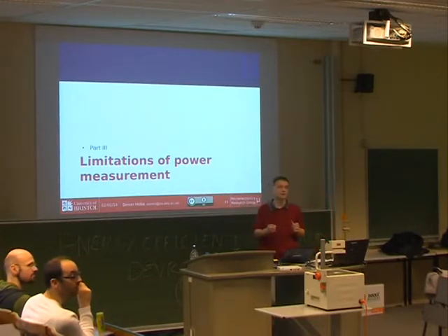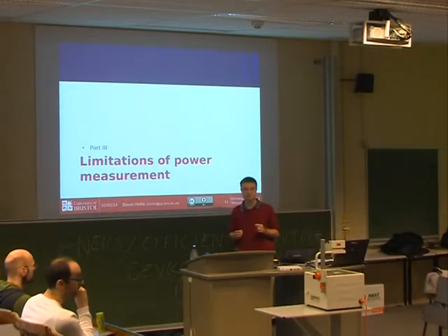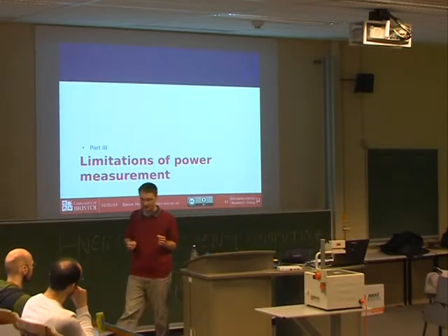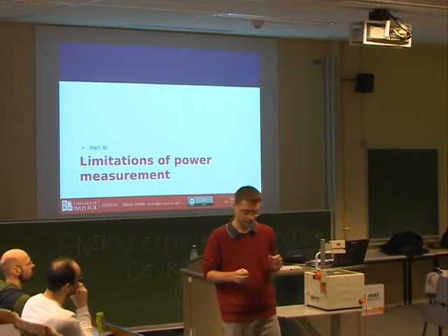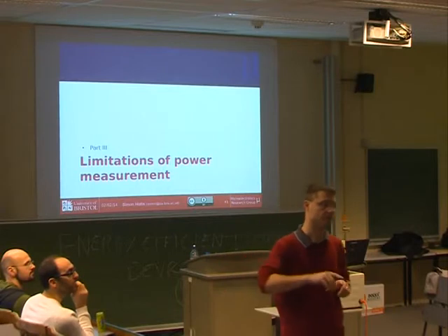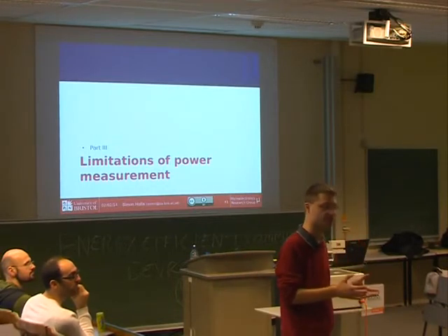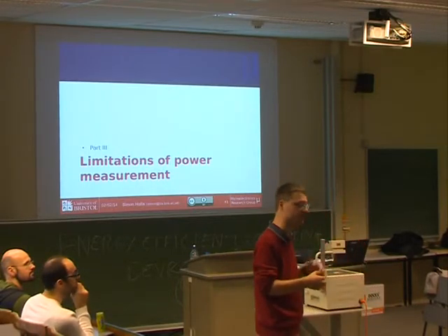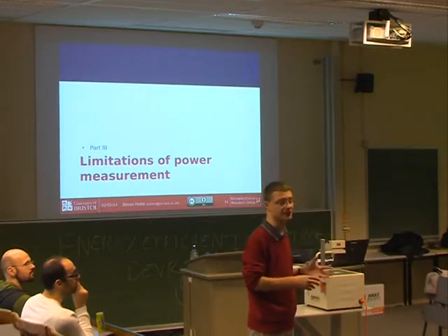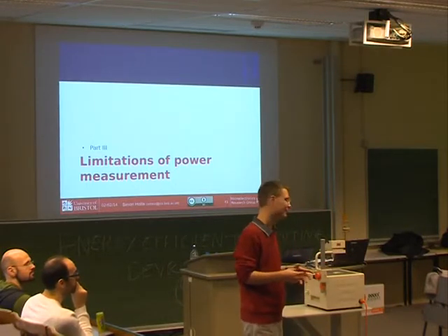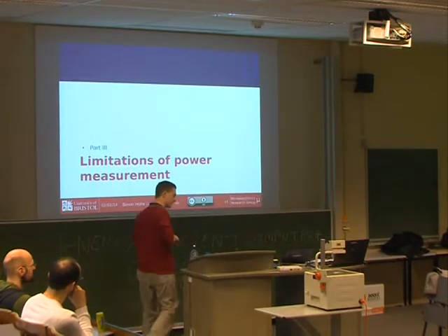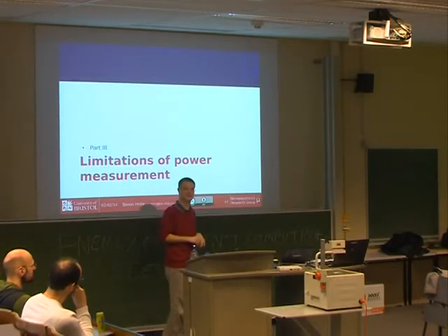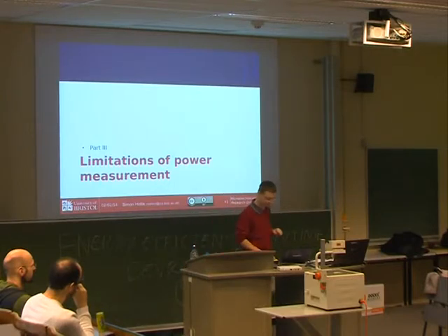What about non-linearity of the ADC? Do you take that into account as well? That will be specified in the data sheet. Typically, they are internally calculated to produce a linear output when you get the binary representation. But these kinds of things depend on the ADC that you use, and you have to read the data sheet. It's always a caveat. So you normally get a linear binary representation, even if it's not a linear response from the ADC itself.